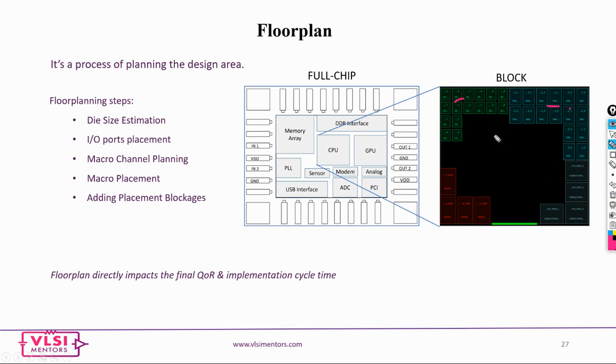Your standard cells are not placed yet, so they are all sitting at 0 0. During floor plan, or any time before placement, they would all be sitting at 0 0. Any design will have IPs, macros or memories, plus standard cells.